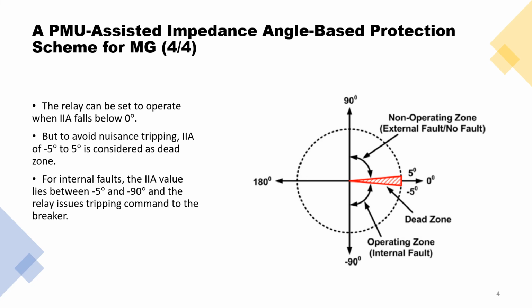But to avoid noise and tripping, the authors recommend that an integrated impedance angle of -5 degrees to +5 degrees be considered as a dead zone.